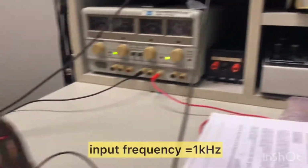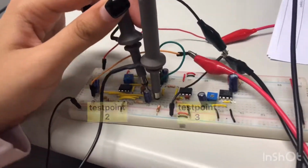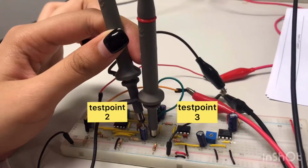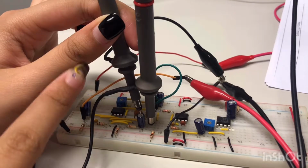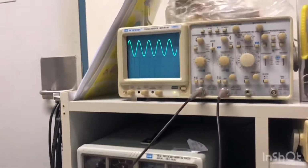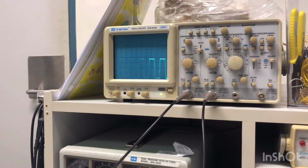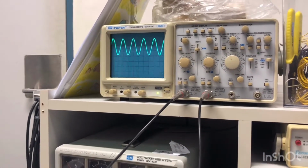In this video I'll be testing from test point 2 to test point 3, testing whether the potentiometer is working. Channel 1 is connected to test point 2, and channel 2 is connected to test point 3. Now you can see there's a square waveform. If the potentiometer is working, it should be able to trim my output waveform to a sine wave.